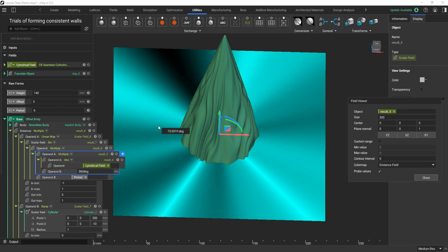The reason I'm switching things into degrees, just to give you a heads up, is that we're working towards a trigonometric function. I'm going to use a sine function to get these really funky waves. You could do this in radians, but I find it easier to do it in degrees. I have to create this field space in degrees so that I can use that sine block.